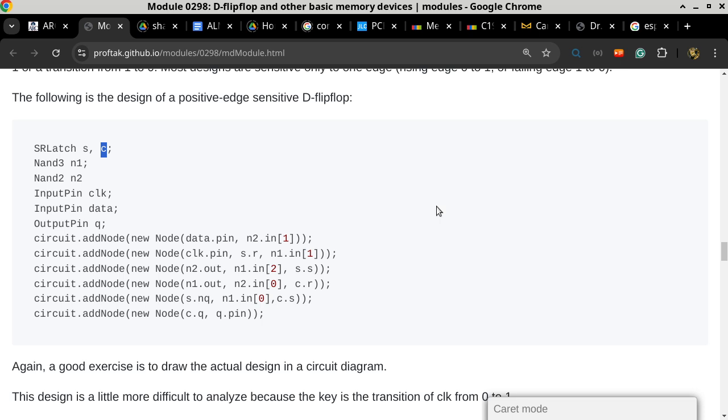You mean for output or input? Nope. For the output, you can simply leave it unconnected. Yeah, it's safe. Nope, because there's no current. You have a voltage being present at the pin, but because it's not going anywhere, there's no current. So it doesn't draw any more power than usual. It doesn't cause any interference. It does not cause any, you know, EMF, EMI, electromagnetic interference. So it's okay. It's not a problem.